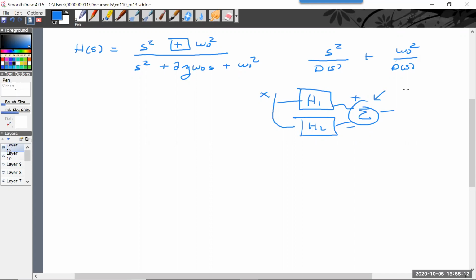Right. And the summers, right? We know how to create those already. Those are op amps. So zeta is a damping coefficient. And if you remember over, under, and critically damped, a zeta equals 1 is critically damped. Zeta less than 1 is under damped. There's complex roots. Zeta greater than 1, 2 different roots. Okay. Now, to show you the oscillations, I'd rather wait for another time.